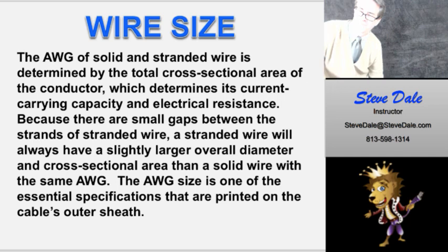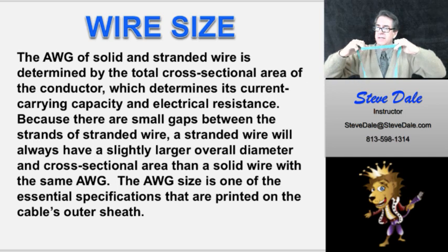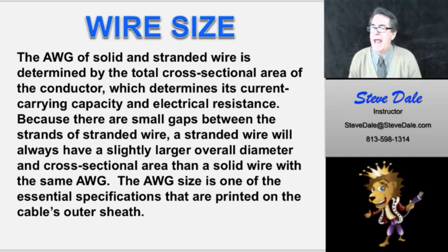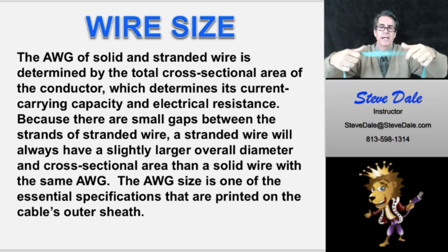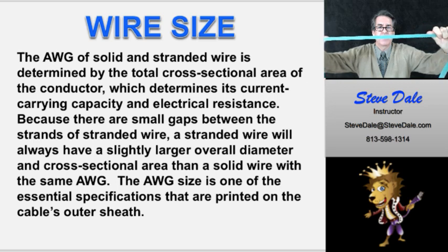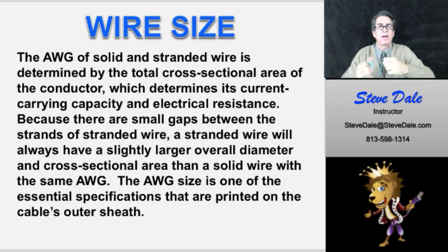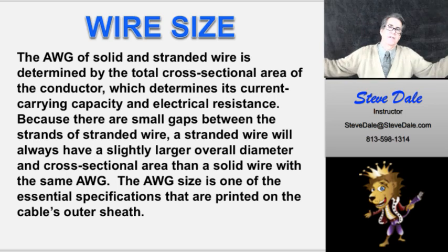I just happen to have this box over there that I take to my workshop. I just like to show this. This is a rubber band, obviously. Basically, wire is drawn through dies, and each time they draw it, like this rubber band, say it comes in a square ingot, and it's pulled and stretched. When you stretch it, it gets thinner and thinner, just like bubble gum. The more I stretch it, each time it goes a little bit thinner. With wire, you can't just stretch it because it breaks.